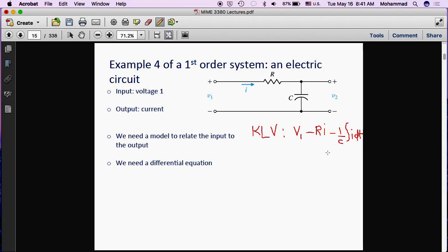And that is equal to what? So you're adding voltages and voltage drops. That's equal to what, according to Kirchhoff's law? It is 0. If you go around a closed circuit and add voltages, they have to add up to 0. Otherwise, you're saying voltage comes from somewhere. Basically, the law says voltage doesn't come from anywhere other than your sources and then the drops due to loads. So that adds up to being equal to 0.